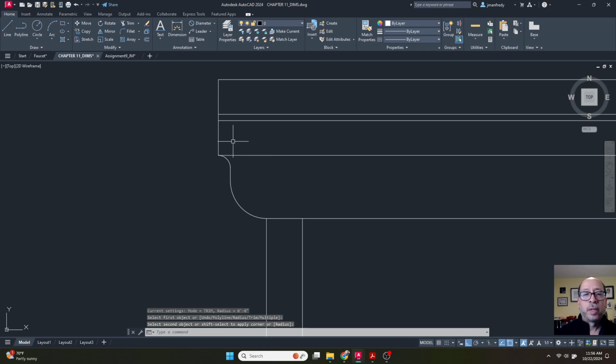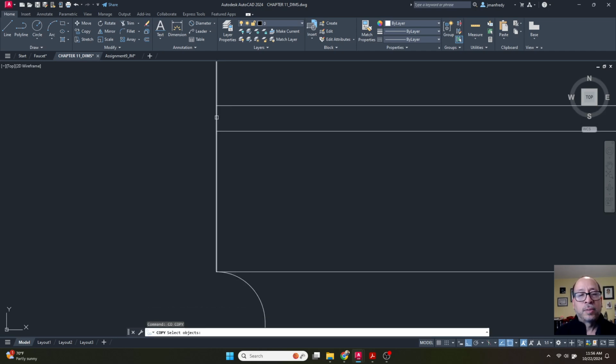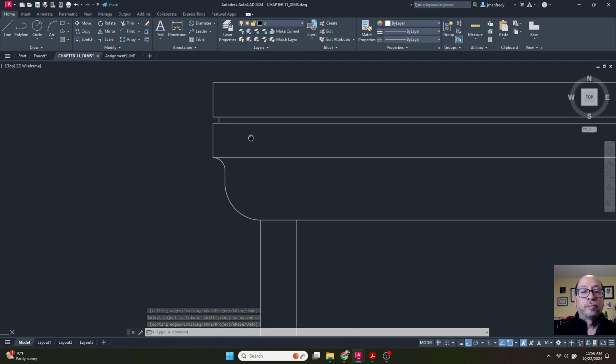And this is what they're saying here. This should be set back, obviously set back here 1/8 of an inch. And then TR for trim to trim off all the parts we don't need here. This little groove is at the face of that top piece of the cabinet there. So that's the design, because that is 3/4 inch and that is a 1/4 inch. So there must be a flat part in here to get to the measurements that they're describing in their detail.